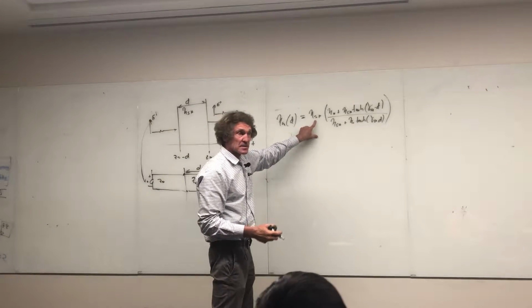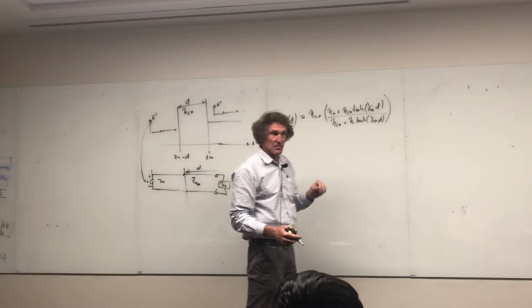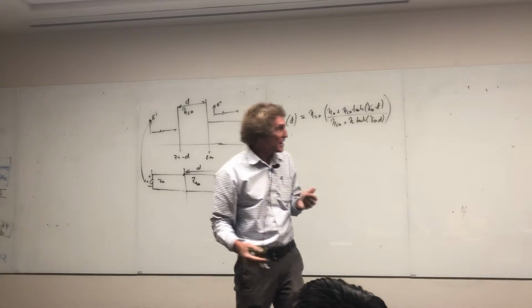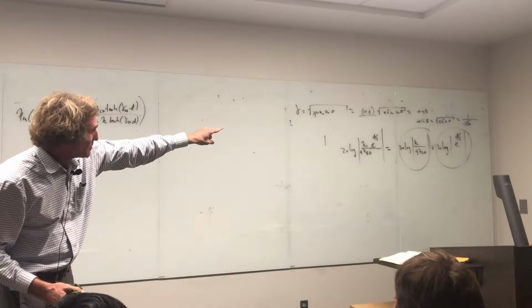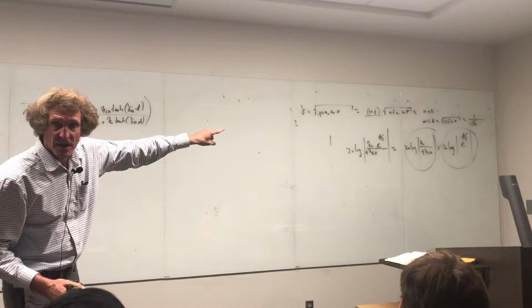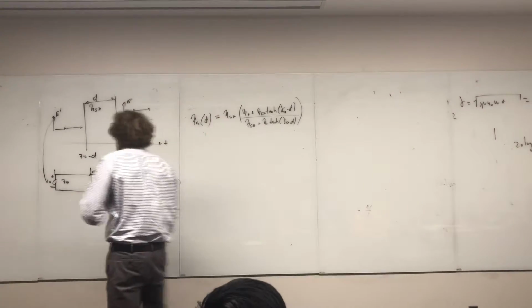That's complex. Eta naught is 120 pi. Gamma is gamma of the shield. The one thing you remember with gamma of the shield, it's 1 plus j times, it's over there. See that right there? It's just simply 1 plus j times 1 over the skin depth. Can you all see that? So that's what gamma of the shield is, and that's the input on the shield.